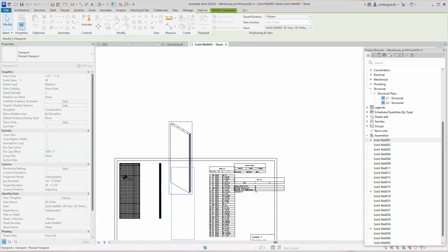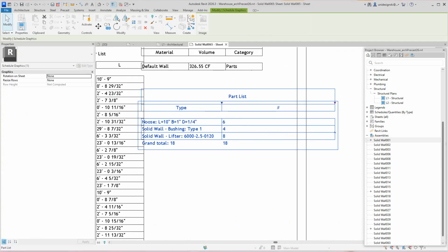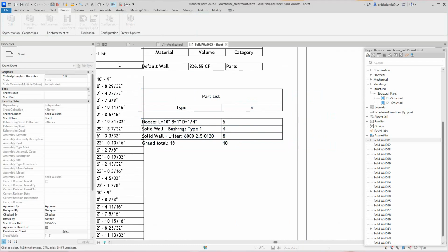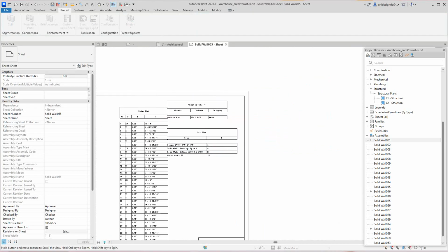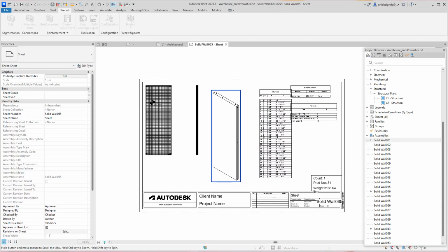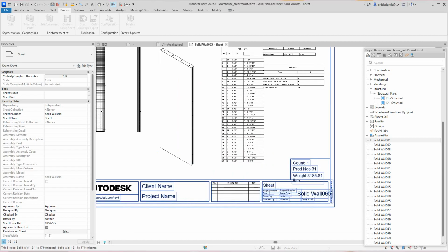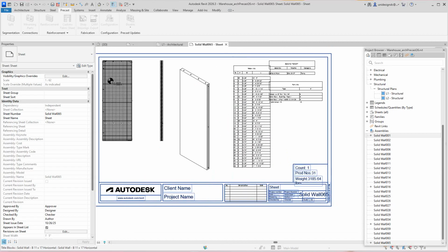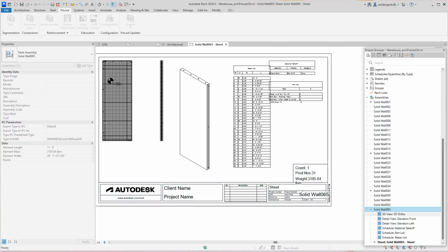And move that there. What this does is generate all your sheets and give you all of the information. That's your rebar number. It tells you the total, so it gives you all your information for that sheet, for that panel. So here, this is number, let's see, that's number 65. If I go down to 65 and expand that, that's what the sheet will generate in views.